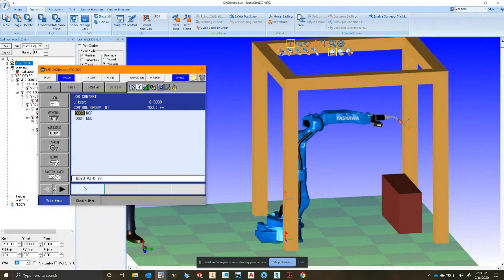It's more precise. If you are handling, you'll want to use linear moves for the fine detail, like approaching the part you're going to pick and the place and drop off locations. But for the transfer point, you can use a joint move, it'll be faster. But for here, we're just going to trace this box. So we're going to stick with linear.